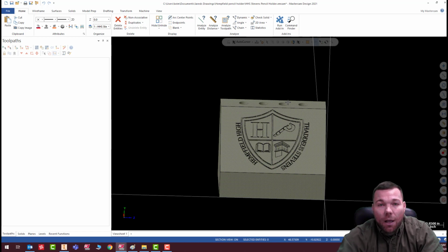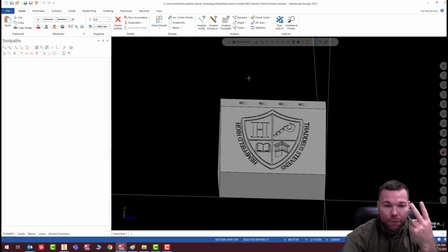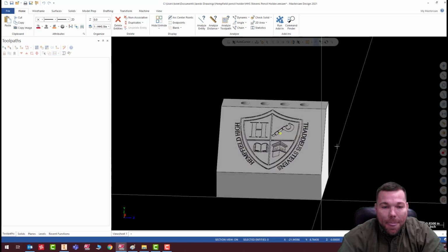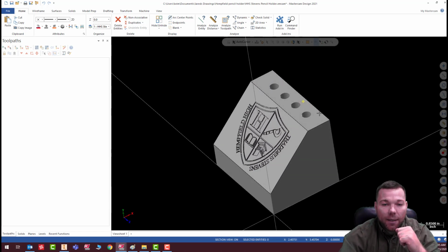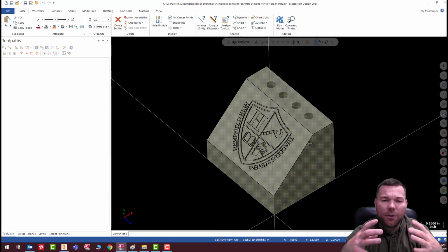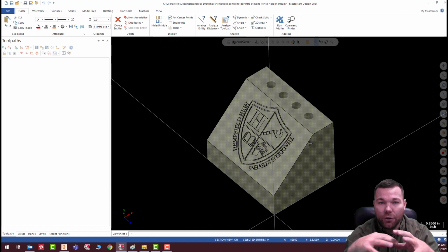But we have the technology here at Thaddeus to make this in a 5-axis machine, which we can reduce those amount of setups down to 3. And in those 3 setups, only 2 of them actually affect the size, fit, form, and function of the part. So, we're going to set this up at a 5-axis. So the first thing I'm going to do is, in the 5-axis, generally what I do is I use the very center top face of my part to create my 0. So my 0, 0 is going to be in the top center.